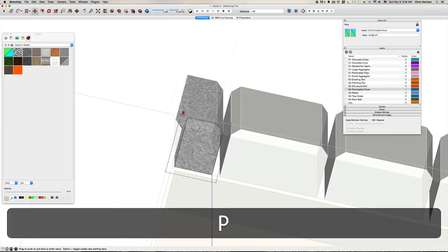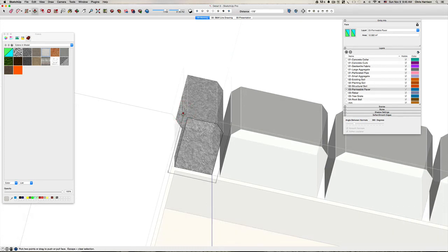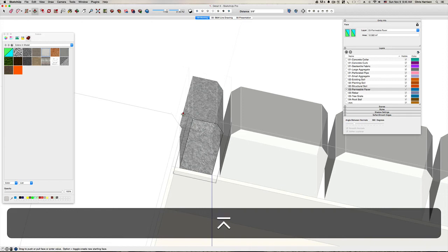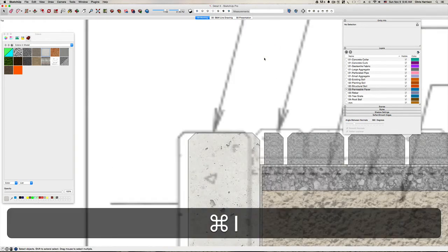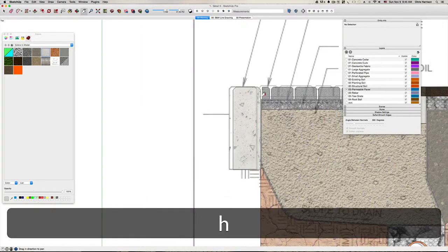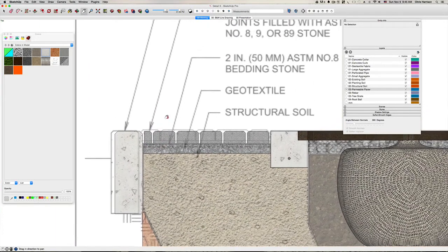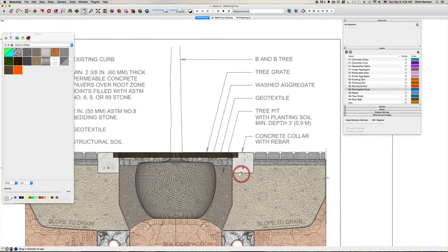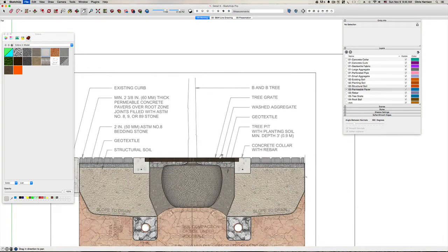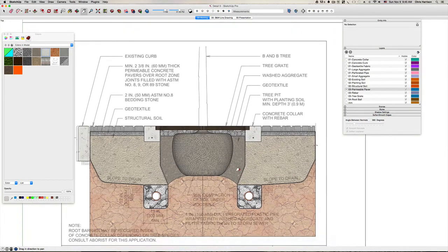Okay, so I'm just going to squeeze that over too, and I'm going to do it, what did I say, 3/8. Okay, and that's going to be our brick there. I'm going to go back to plan view so we can see. That's going to represent that cut for me, and I'll fill all these joints there as well. All right, so that's cool. So we have that. I'm going to save. And now let's begin to extrude some of these pieces.